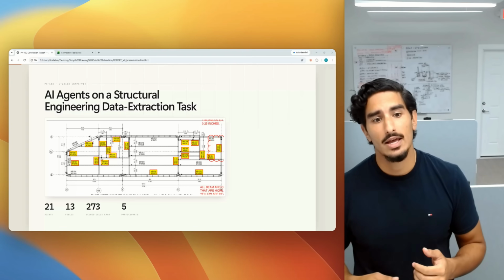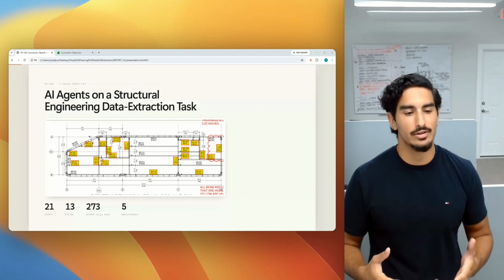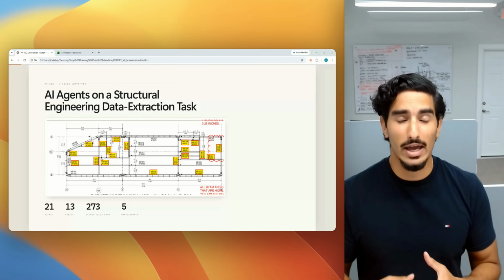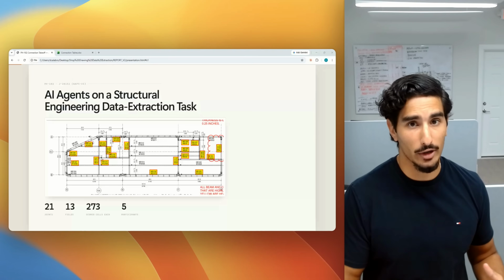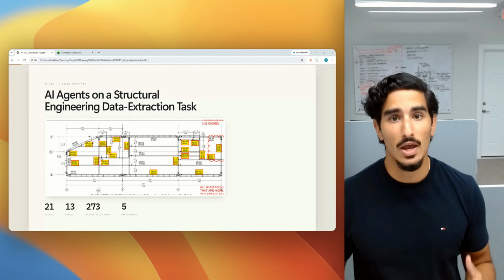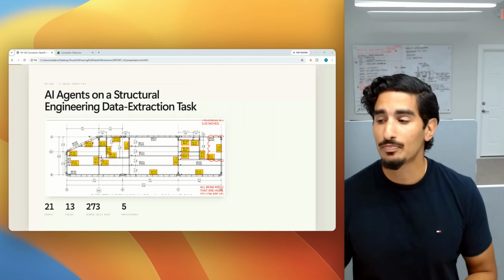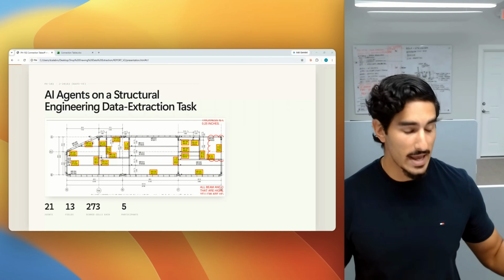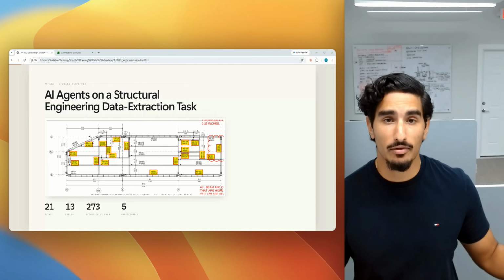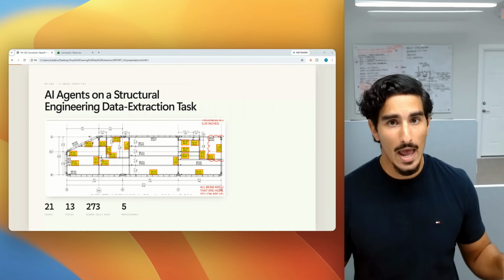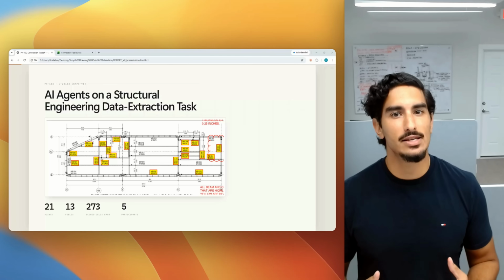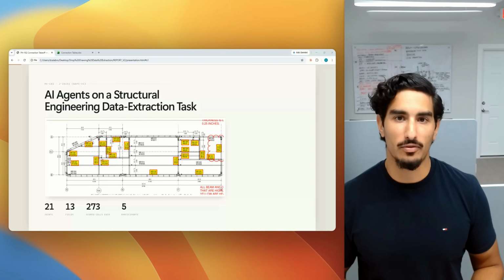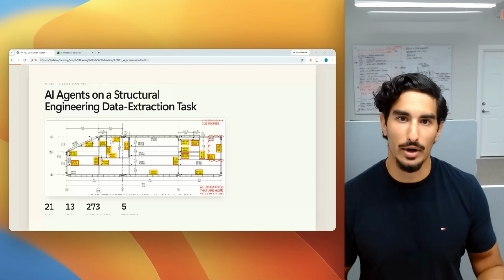All of that being said, what this workflow entails is I'm acting as a delegated design engineer for the engineer of record. We're working on a steel frame structure. And my role in this job is to look at the existing structural system, take the new loads that we're getting from the engineer of record, and assess the capacity of the lateral force resisting system and figure out whether we need to reinforce different types of connections or not.